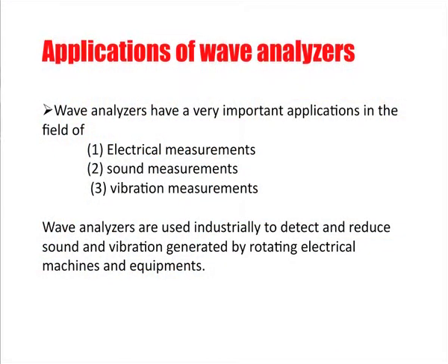Now, coming on to the applications of the wave analyzers. The wave analyzers have very important applications in the field of electrical measurements, sound measurements, and vibration measurements. Wave analyzers are used industrially to detect and reduce the sound and vibrations generated by rotating electrical machinery and equipment. In industries there is a large amount of noise which is generated due to the movement of the motors or other rotating equipment.